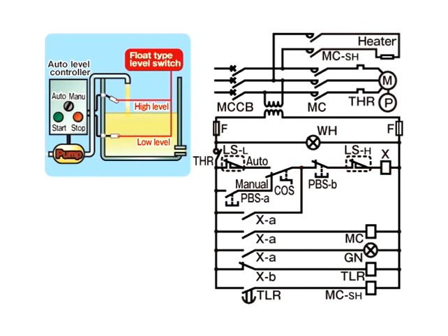Further, let's assume that current exceeding the rated current is passed to the motor during pump operation. Possible causes include the motor having stopped because of damage to a bearing, or a large quantity of dirt accumulated on the vane in the tank has caused the load on the motor to increase tremendously. Let's see sequence circuit operation under these conditions.